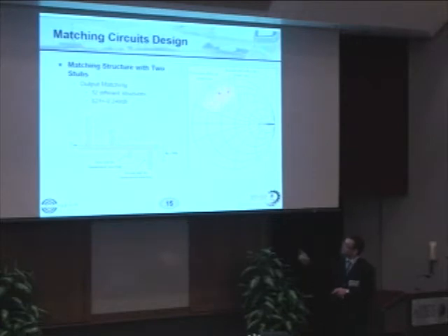Here is the design of the matching network. As we can see, the first stub is for the second harmonic, the second one for the third, and the third for the fundamental, and the second and the fourth are for the fundamental and for biasing. The loss of the matching network is optimized, and out of 32 different configuration structures, we chose the one that presents the lowest loss.